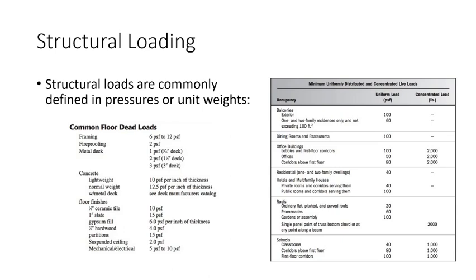Let's say I'm trying to design the floor beams holding up not just this ceiling, but the floor above. What do I have to account for? I have to account for the drop ceiling, the lights, the mechanical, electrical, plumbing, fireproofing, the structural frame itself, the metal formwork, the slab, etc.